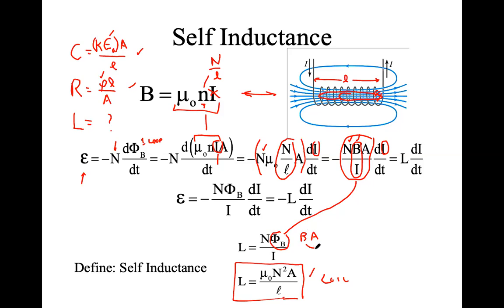Okay. What happened to the negative sign on the coil? Good question. Always a good question there. When you're trying to decide that negative sign, I think I said last time, I ignore it. And it's a little sloppy, but what is the significance of that negative sign? It means Lenz's law is in effect. It means the polarity of the voltage is going to be such as to oppose the magnetic flux change which creates it. And so L is just a positive constant. That negative sign, I just ignore. If you want to put it right in here, you can.